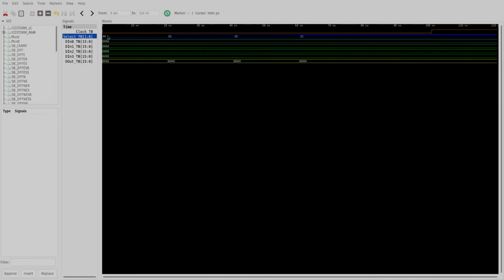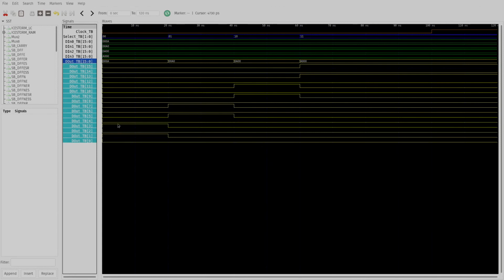As in the test bench, we set up our select statement to 0. We set each one of our inputs to those letter A's as they move along to the left side. In this case, we're not using a clock, we're using Verilog's delay. And here is the output of the first delay as we switch the select statement to 1, then we select 2, and then finally 3. And we can see that the letter A is going. If I double click this, you'll see that the pattern is moving along the inputs. And there you go, our MUX seems to be working.